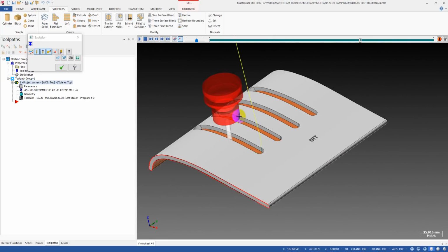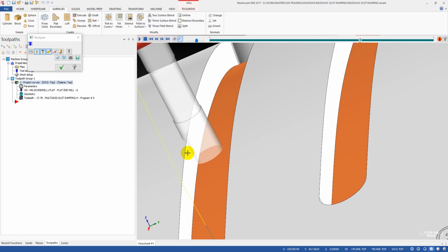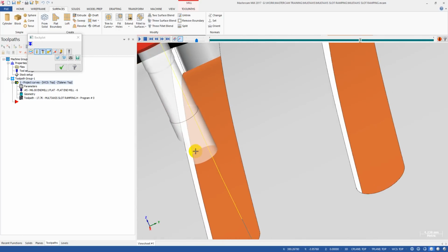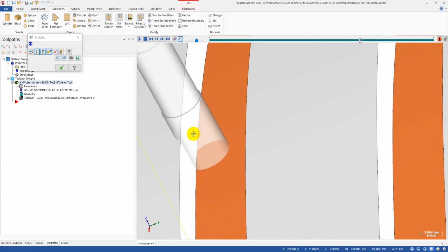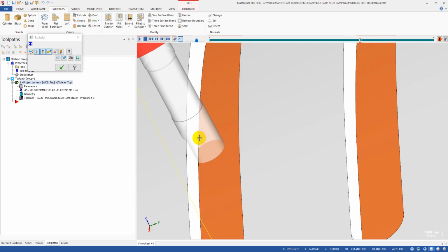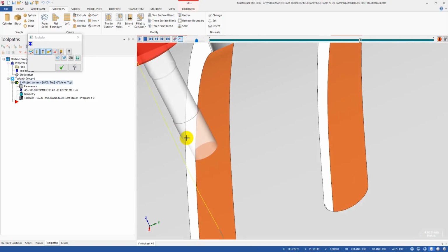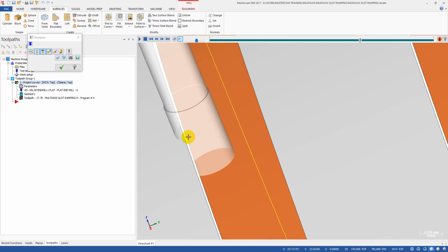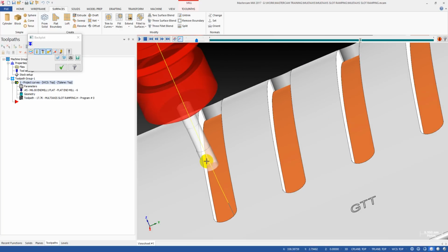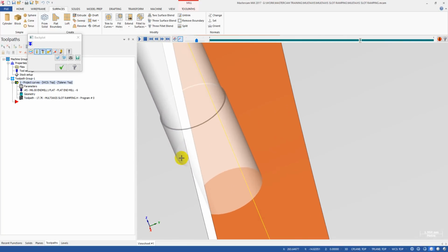All right, take a look at this. You see the problem. When you input a -1 value for the surface offset, the tool will also go far away. It will go through the curve here. It is not in contact with the wall anymore, and now it cuts further into the wall here.